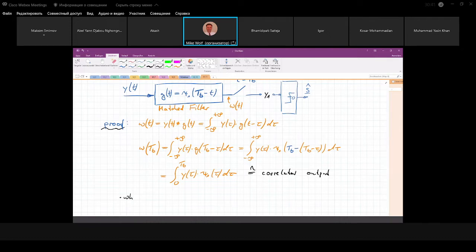We get the signal component at the output is a square root of an energy. So in practice, you can detect a voltage, but not a square root of an energy. This is just a model. You can scale it, and then everything is fine. Any practical filter has basically a scaled version of this impulse response. The shape is the important thing.